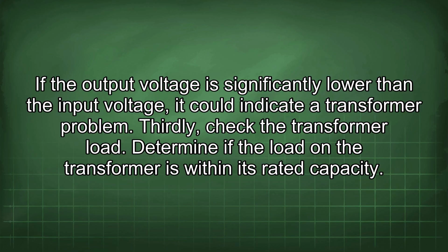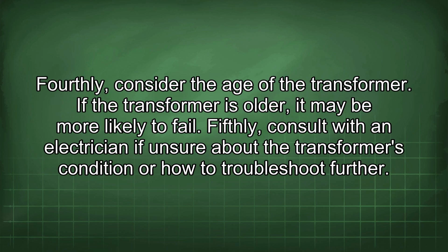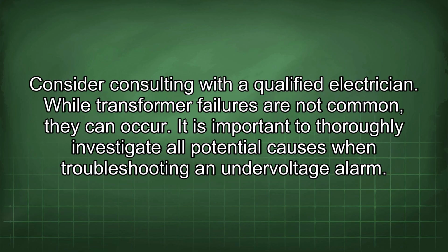Thirdly, check the transformer load. Determine if the load on the transformer is within its rated capacity. Fourthly, consider the age of the transformer. If the transformer is older, it may be more likely to fail. Fifthly, consult with an electrician if unsure about the transformer's condition or how to troubleshoot further. Consider consulting with a qualified electrician.